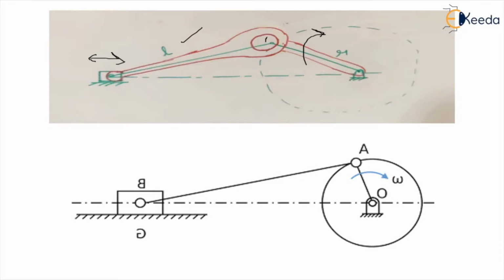Therefore, if we want to replace this connecting rod with a dynamically equivalent system which does not have a correction couple, I'll show you a separate diagram, we replace it with a massless link with 2 point masses, let's say M1 and M2, in such a way that the mass of the connecting rod M is equal to M1 plus M2.